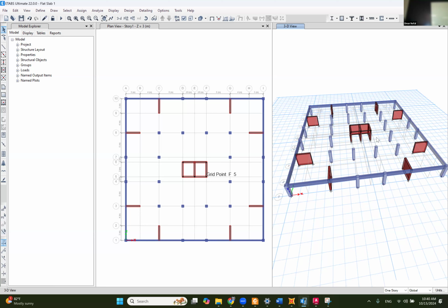You can actually make it for all the beams in your cross section, but the analysis is going to be more complicated. We need the analysis to be accurate at the shear wall location. Okay? Because we're going to talk about the coupling beam later, maybe next week or something. All right. So I'm done with everything except the slab system.